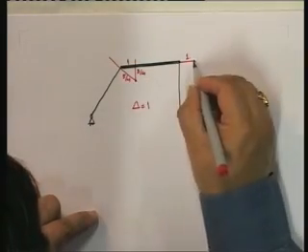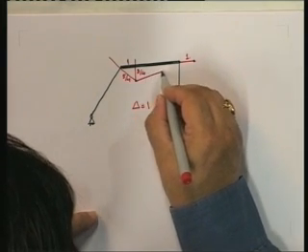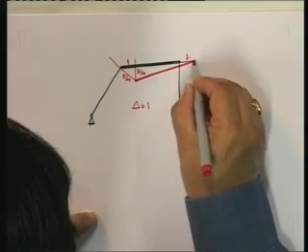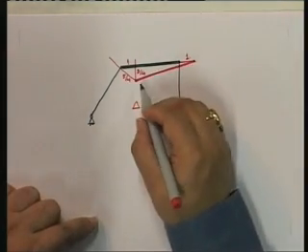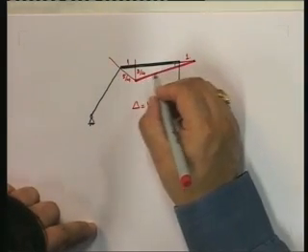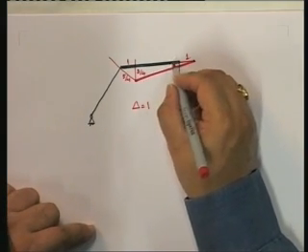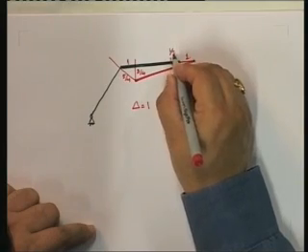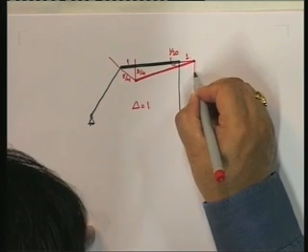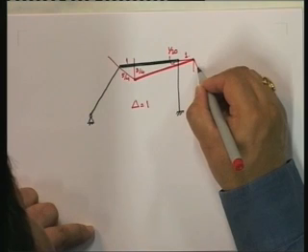Now since point B has moved here and C has moved here, now this member has to remain straight because it is a rigid member. A rigid member can only go straight, and since this angle then becomes 3 upon 4 divided by 15, so this becomes 1 by 20, and therefore the tangent over here automatically has to follow this.